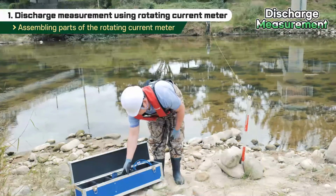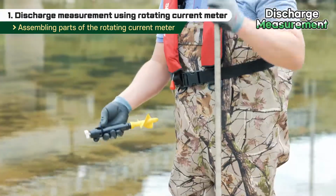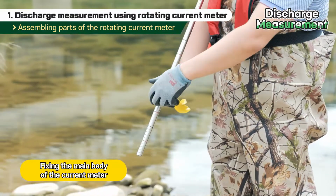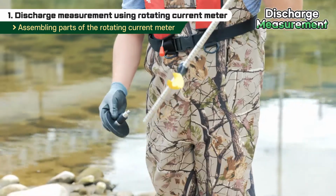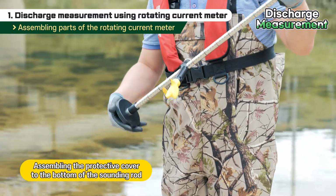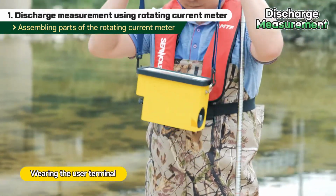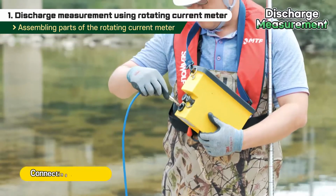To assemble the rotating current meter, the sounding rod is assembled first, and the main body of the current meter is fixed on the assembled sounding rod. While fixing, be careful that the current meter does not fall out of the sounding rod. Finally, the protective cover is assembled to the bottom of the sounding rod. After assembling the main body of the current meter, the on-site worker wears the user terminal and connects the main body of the current meter to the user terminal using the cable.